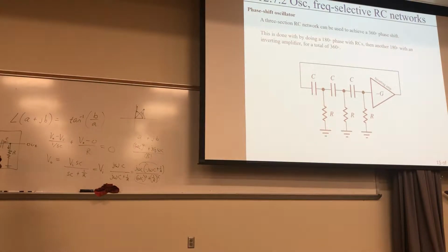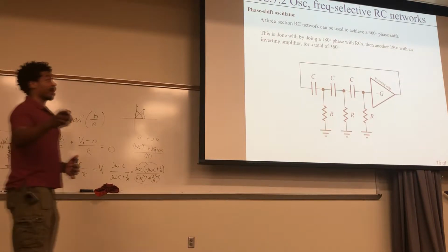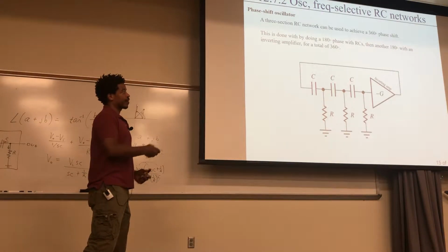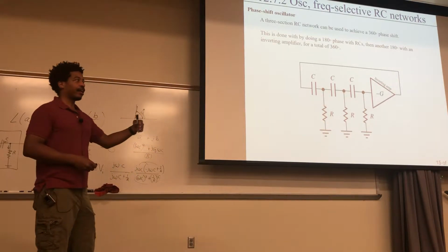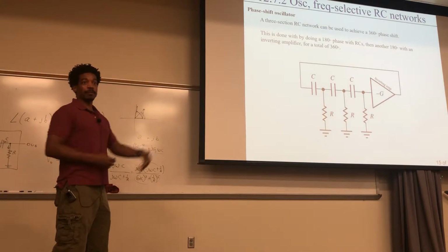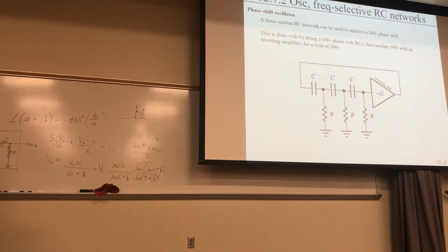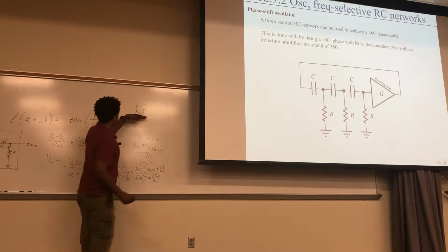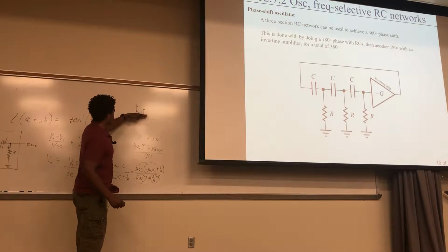However, you wouldn't have your oscillation though, because the op amp gives you your oscillation. Yeah, but yes, you're right. You could do all kinds of things like that. Daisy chain more of these RCs together and get some kind of phase of any angle you want if you have enough of them. That's right. Yeah, because each one can give you any range from 0 to 90, right?